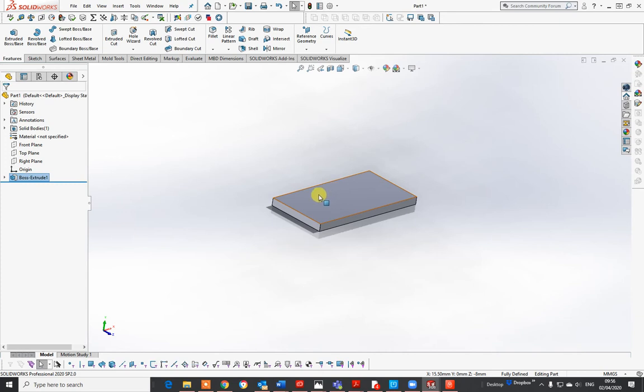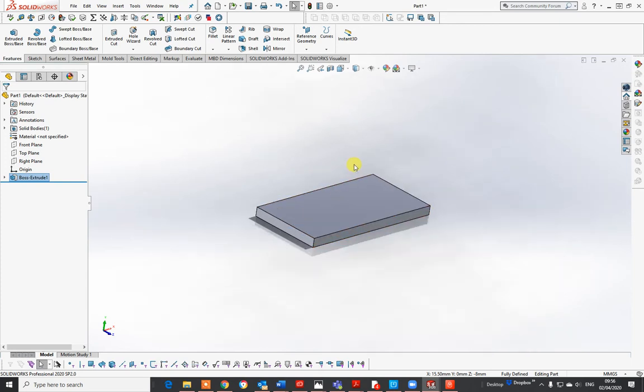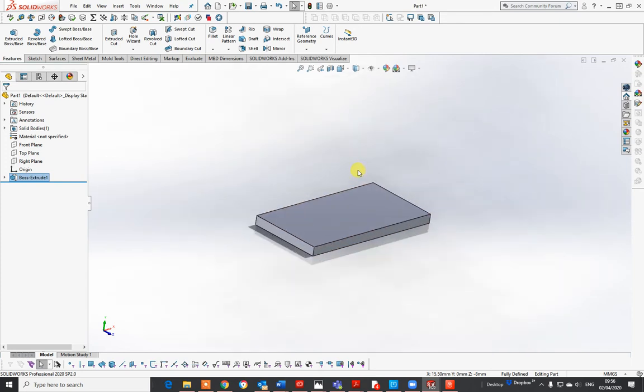Now, if you look at your drawing, you'll see there's a height from the bottom, that point there, to the sort of shoulder of the Lego man of 12.8 millimeters. So what I want to do now is create a plane of 12.8 millimeters. So if I go on to my features menu, which I've kind of lost, it's actually, yeah, I'm on my features menu. Go to reference geometry, and it's the little icon there, same plane. So I click on plane.